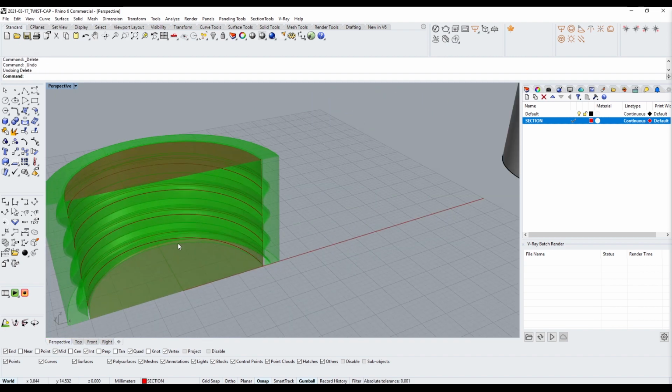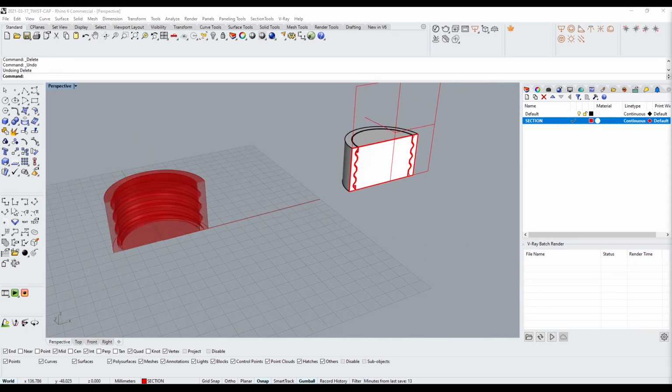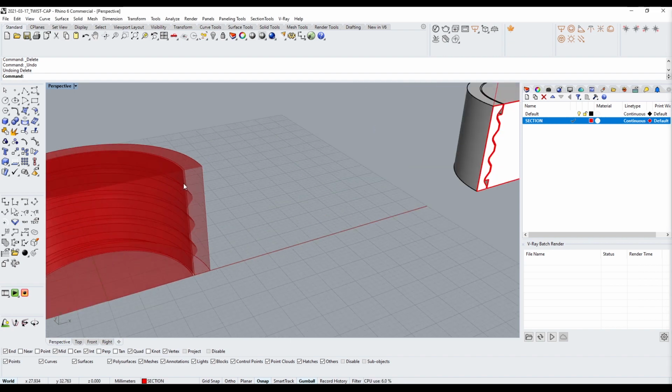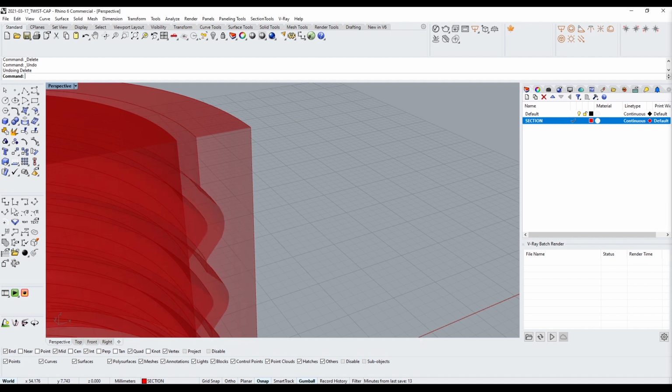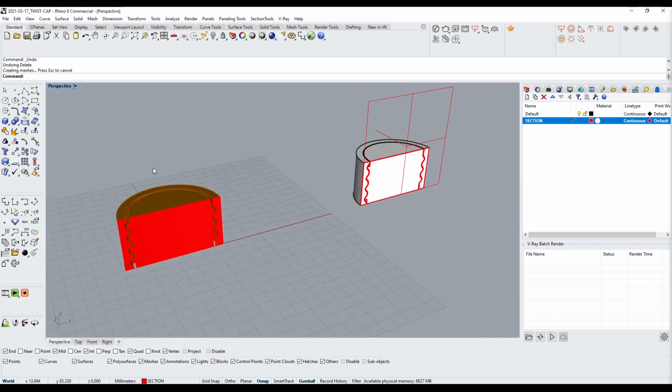actually let's do this. Let's change the tolerance. So I'll go tolerance offset and I'll say 1. And tolerance offset on this one, I'll say 1. And I'll take both of these and bake them and see what it looks like when it has a bit of a different tolerance.